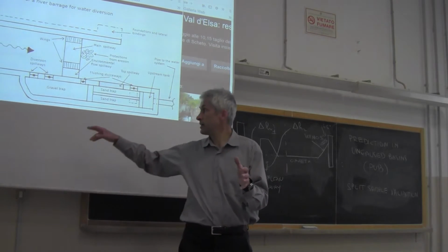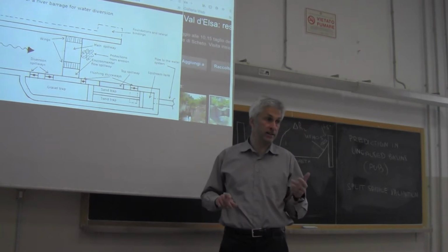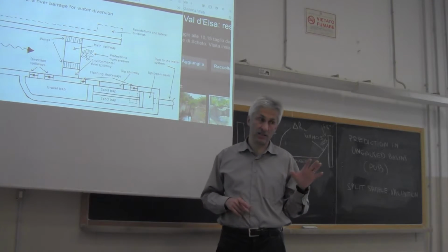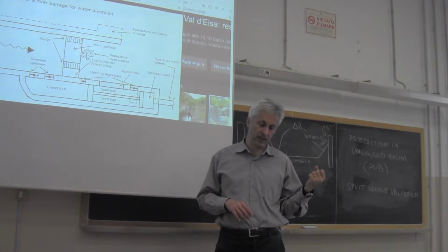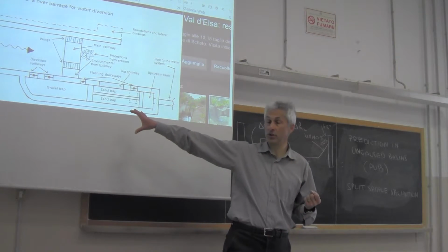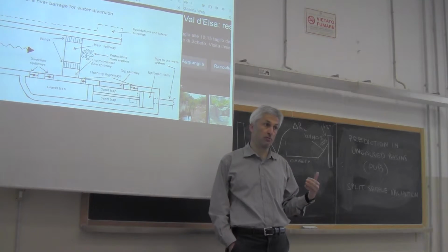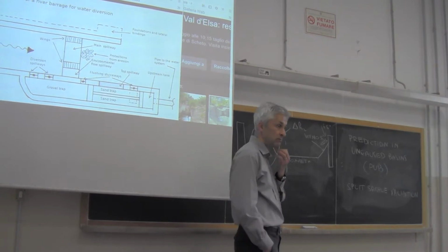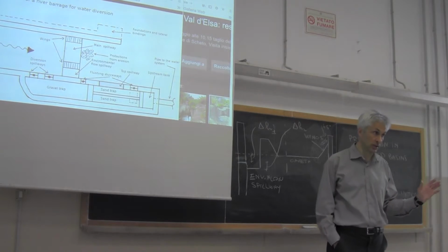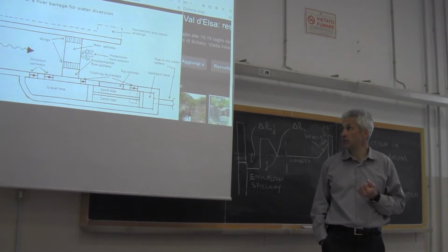And the reason why we want to put a gate here is, as I mentioned to you before, for allowing cleaning, maintenance, etc. And also keep in mind that in some cases it's advisable, if you have a river with strong sediment transport, that you close the diversion during high flows, because during high flows you have more bed load, more sediments transported by water, and therefore you may not want to take that water. Whatever the use is, you may not want to get that water.